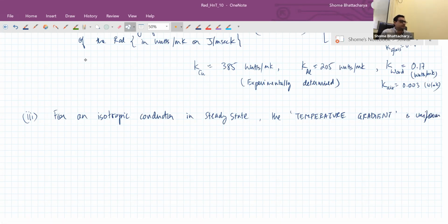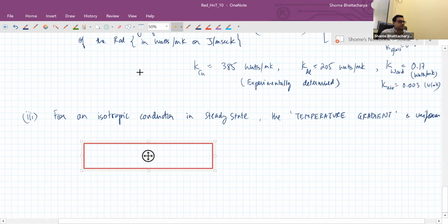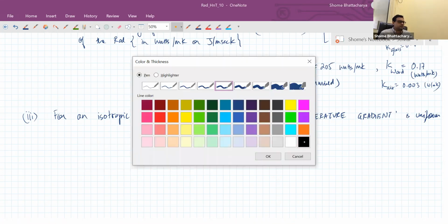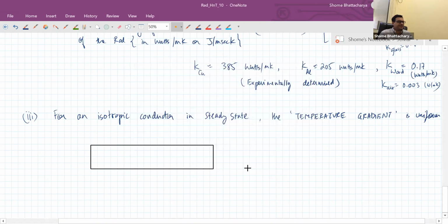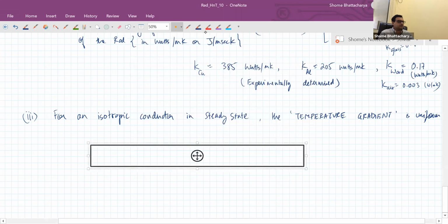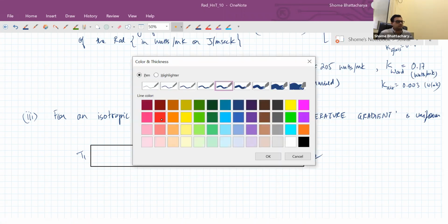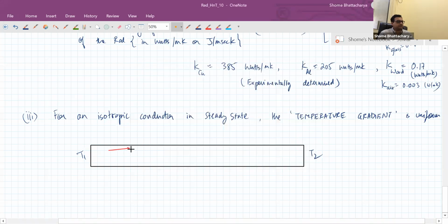And there's a very easy way to understand why this happens, a sort of proof of this. So if we maintain our heat conductor with the two ends at constant temperatures T1 and T2, such that it's in steady state, there is a uniform rate of heat conduction happening through it.